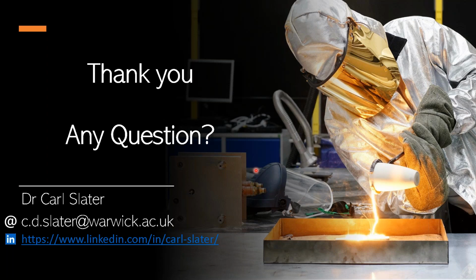Yeah. So the good thing about working with small samples is that they tend to cool pretty quickly. So we have entire control over it. The process itself is quite manual. So whether we're doing casting, we can use water-cooled molds. If we want to do hot rolling in the mill, or whether doing it on the Gleeble, we can always use a quench medium. So understanding the individual parts in more detail, quenching is an absolute must.